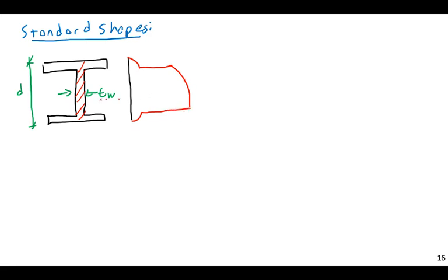There's a massive increase. I don't like how that looks. Let's do something more like, okay, that's symmetric-ish. Going to there and coming back down. Okay, I can live with that. Something nice and tombstone looking. And this then, at the centroid, is tau max. Okay. So, the tau max is approximately equal to the tau in the web, which is less than or equal to tau allowable.